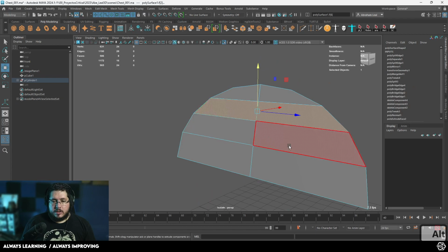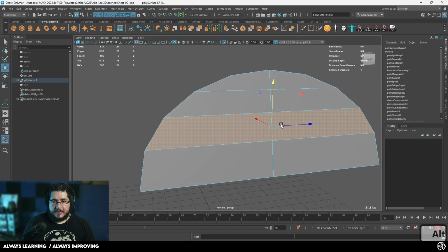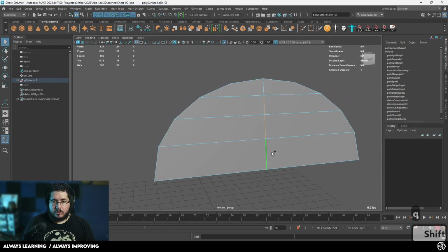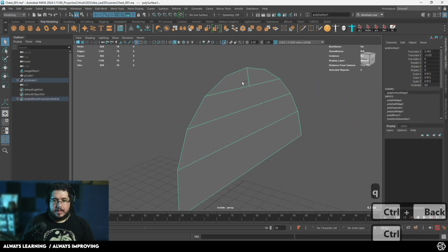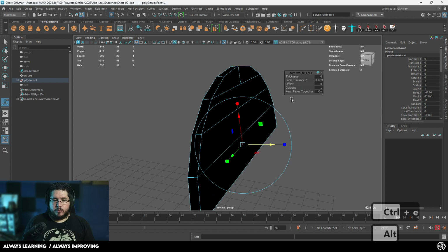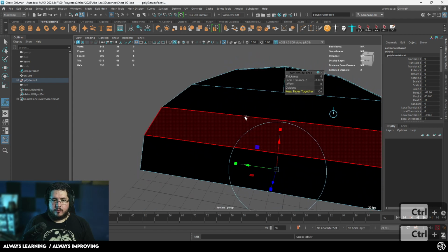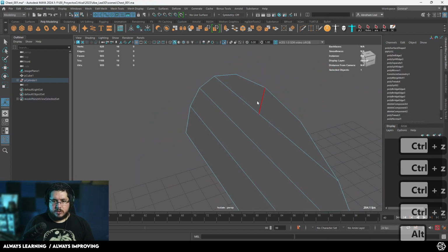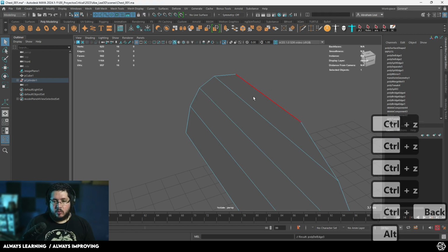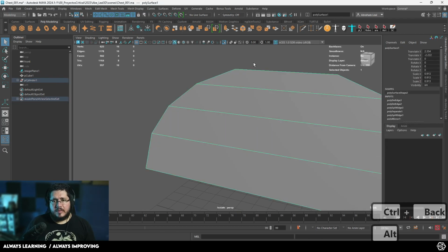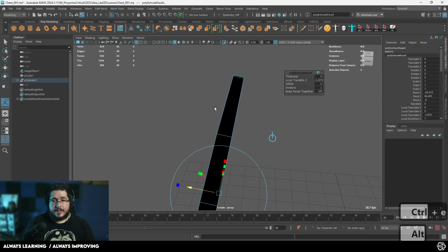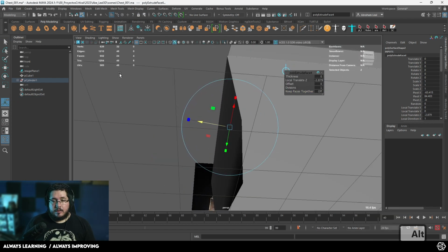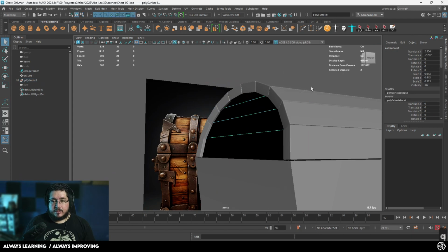If we go to the faces, you can see that all of these faces are split, which is fine. On these ones right here, on the lower ones, I'm going to delete that middle edge. We don't really need it. And we're going to Control E the whole thing. We're going to push out and keep faces together off. Actually, this one's going to be a little bit tricky. I'm going to have to delete this line for just a second. I'm going to, again, Control E, keep faces together off. And we're going to push this in to generate the relative thickness that we have.